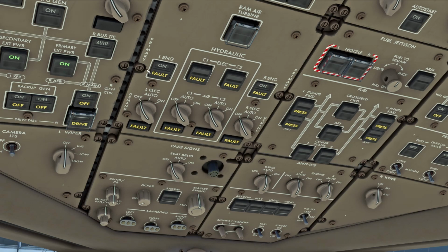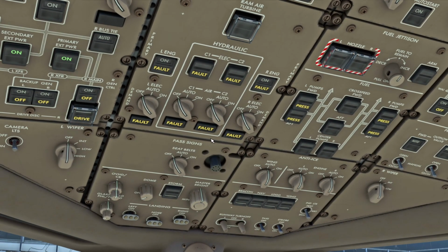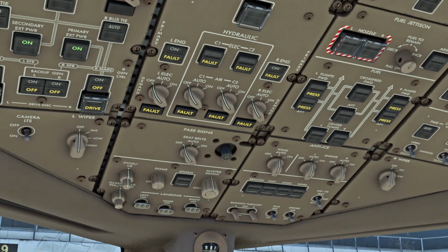Basically, the primary pumps, just like the name says, are the primary sources of hydraulic power of the flight control system. The demand pumps work when the system logic anticipates high demand, or when any of the primary pumps pressure is low. So it kind of serves as a backup as well. Again, this is all automatically handled. We'll put these switches in the right position just before startup.